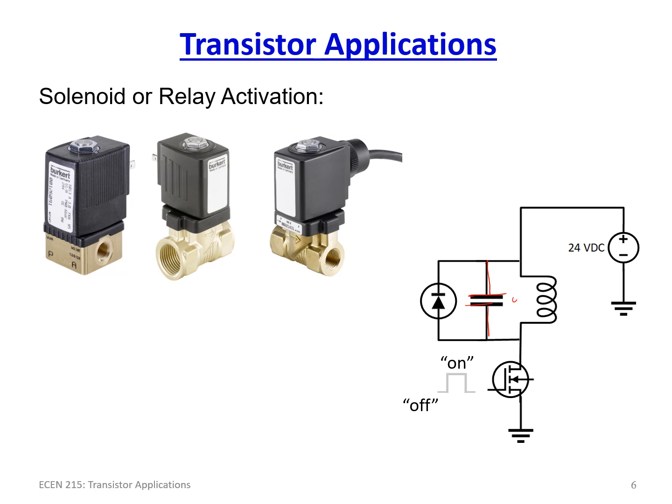Typically, this is in the neighborhood of about 0.1 microfarads to kind of counteract the field, kind of short out that transient spike. And also you put in a diode in the opposite direction because that voltage is going to be generated positive here, negative here. So what ends up happening is that voltage exists now that the transistor is off, and it will short out the coil. So this is basically known as a snubber circuit that you add to your coils to prevent transients from existing on your power supplies.